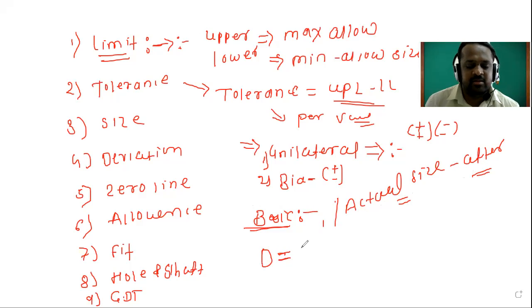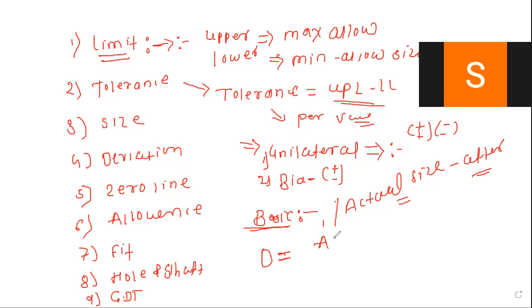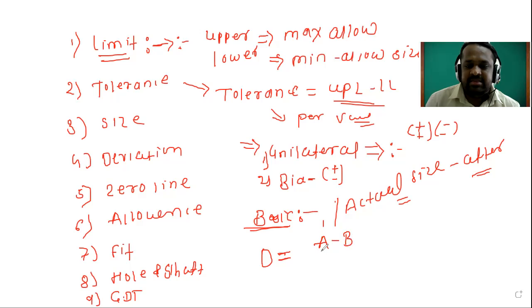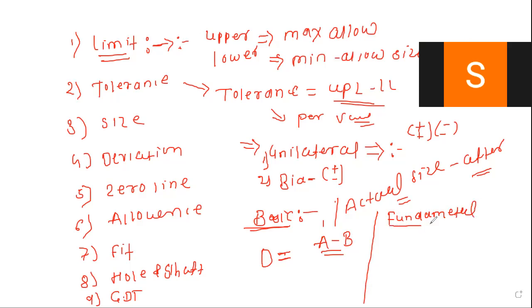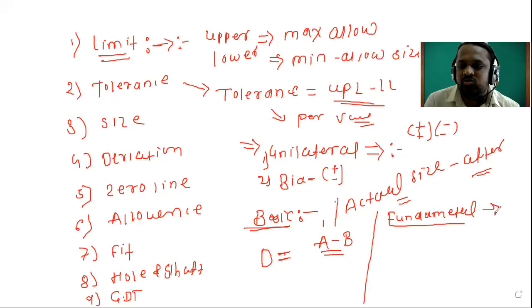Yes, actual size minus basic size, it is called the deviation. Okay, then what is meant by the fundamental deviation? Deviation closer to basic size. Okay, the deviation which is closer to the basic size is called the fundamental deviation.